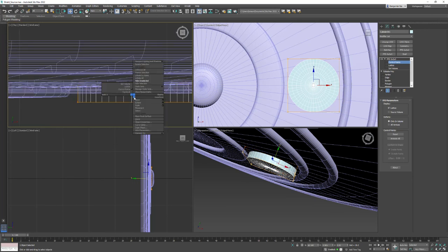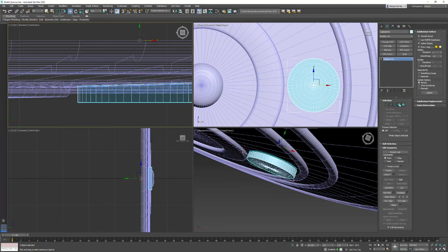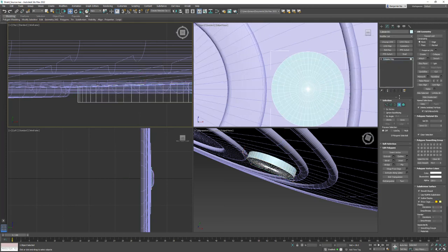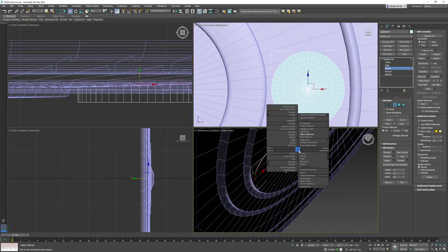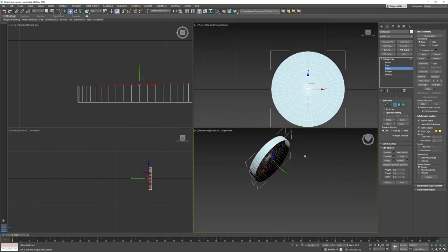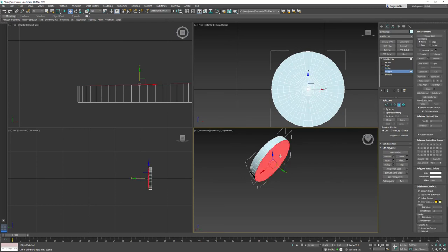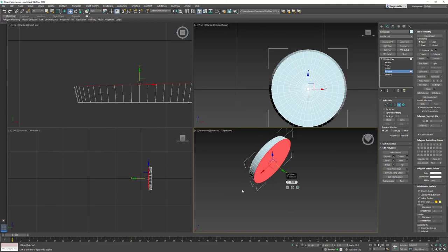All right, right click, rotate poly. And now I'm going to turn on border, and I'm going to select the edges that are on the back side of this. Let's right click, hide and select it. All right, I deleted that polygon on the back, so I'm going to select this, and I'm going to hit cap, go into polygon, click on this, and now I'm going to use outline, and do an outline of like 0.25. It's too much. I'm going to do 0.125 because I want to have a little bit of an angle. I don't want it to be completely straight coming out from the surface.